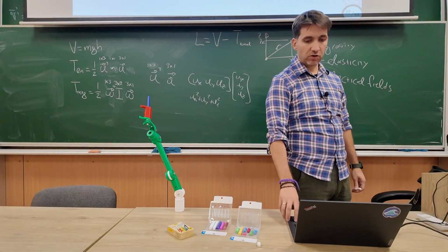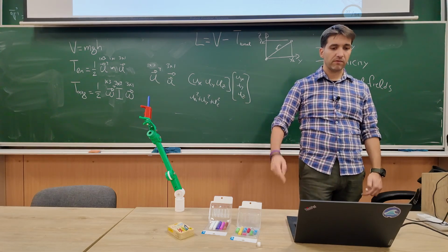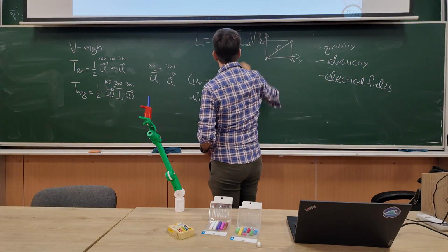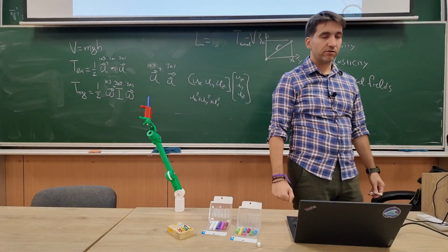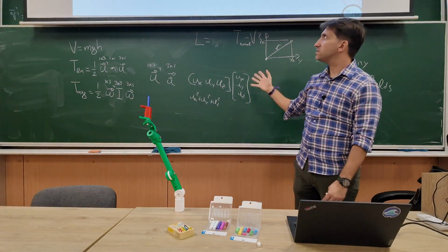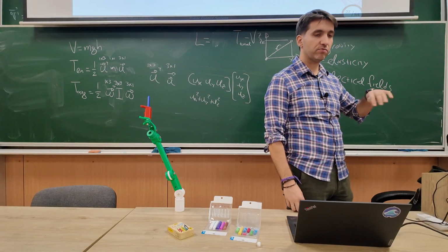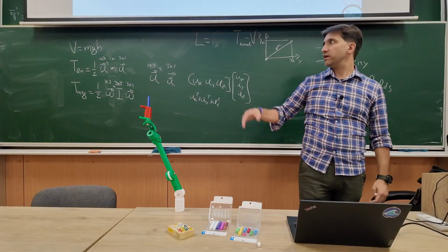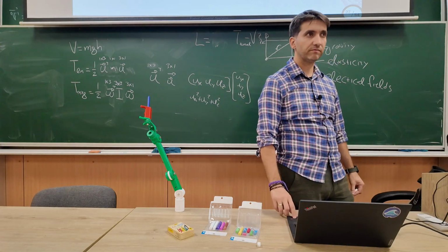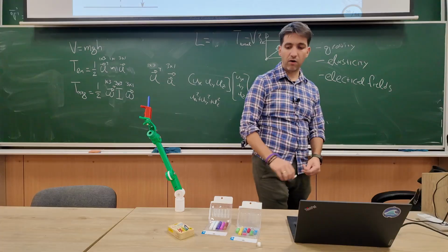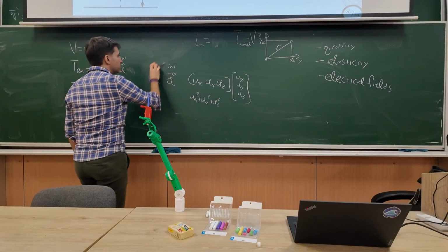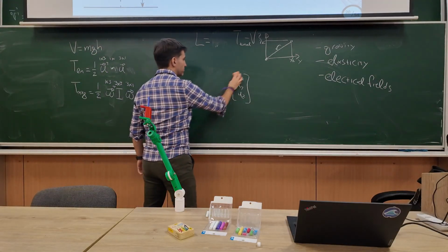Good. So overall, the Lagrangian is kinetic minus potential energy. Potential energy is just due to gravity, mgh. Kinetic, we have to split into linear and angular. For linear, we need the mass and the velocities. For angular, we need these moments of inertia and the angular velocities. All right? Let's see a very simple example of how this approach gives equations of motion with the derivation we saw.